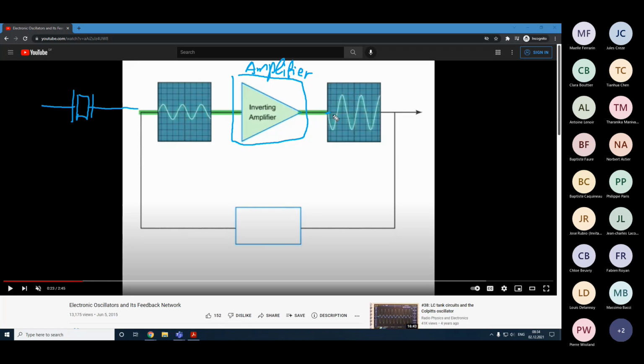We have the signal stronger, but now it's not a plus sine signal, but a minus sine signal, which we are then using for our purpose as a carrier signal, but we also send it back to the input of the inverting amplifier. However, in order for this signal to actually be superpositioned with this, we need to invert it again. So basically what is here is another inverter. So let's see how it works.